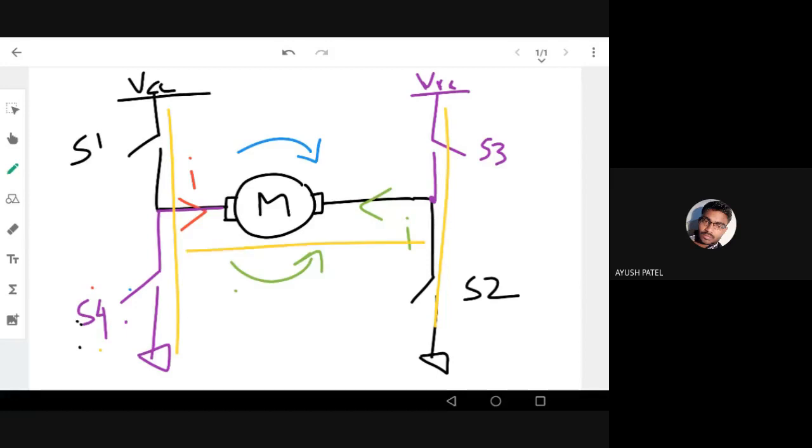So this is a standard robot actuating system, or robot direction controlling mechanism, where the robot will be controlled by a single motor, right? A single wheel will be connected to a single motor and that wheel is controlled by the H bridge. If the current direction is forward, the motor will go in the clockwise direction, and if the current is in the reverse direction, it will rotate in the anti-clockwise direction.